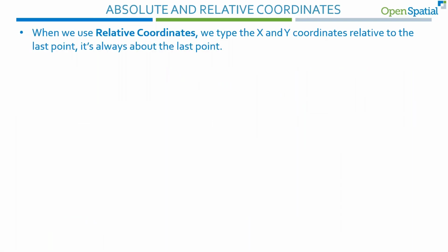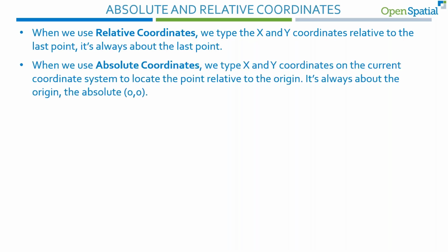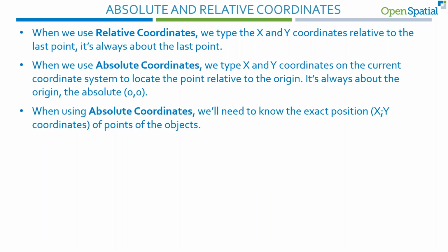Now, working with coordinates, so you've got absolute and relative coordinates. So relative coordinates is offset to a last point. So if I've got a property boundary, you can give it the start point with the absolute coordinates. So you type in the right coordinates that we have. But now we know this next one is 50 feet. So you can then specify a relative coordinate. So the next one is 50 feet. You don't have to work with specifically the absolute coordinates. So you can mix and match depending on the information you have.